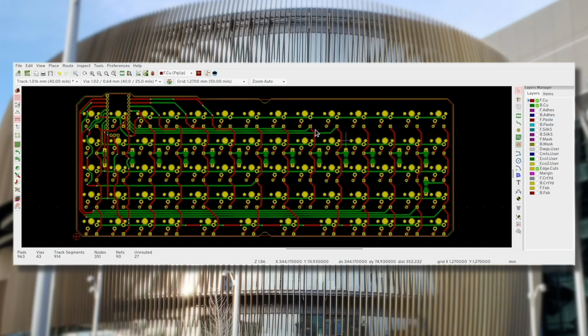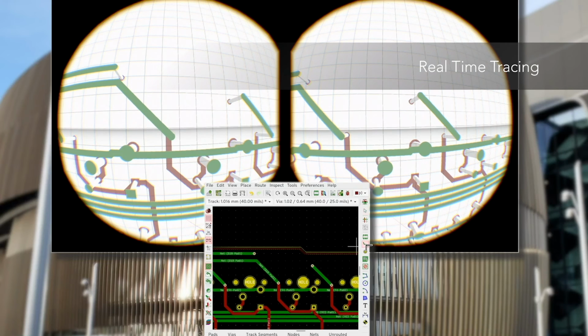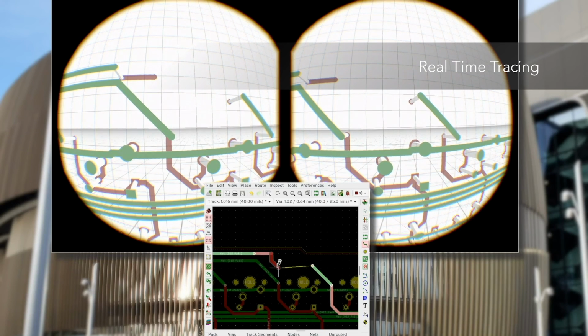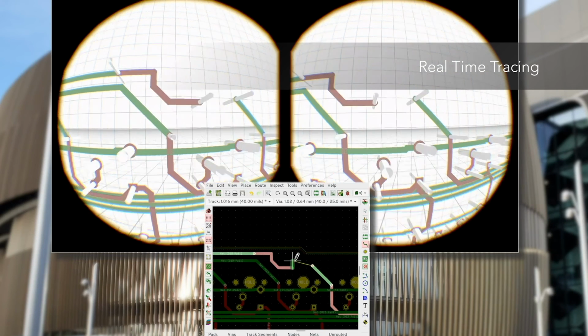Thank you, Anton. Hi, I'm Ashwin, and my work consisted of integrating our project with KiCad. As the goal is to extend the KiCad experience, we must be able to launch the Godot engine for VR viewing from within the application. To accomplish this, we created a launch button in the PCB editor tool within KiCad. KiCad registers changes to a board in the form of what are called board commits. By leveraging the board commits mechanism and incorporating our own logic into the application, KiCad is able to process and send any board updates to Godot in real time, and then instantaneously see their changes reflected in Godot.